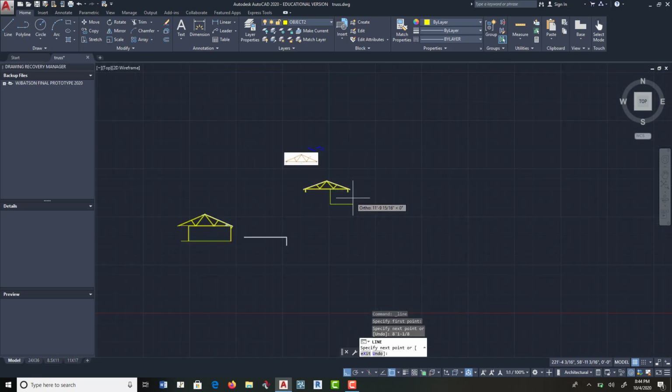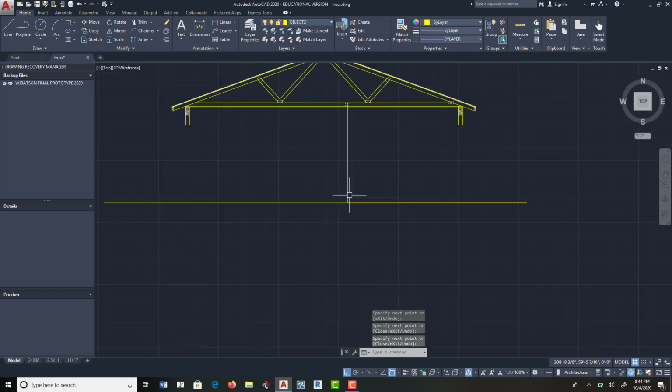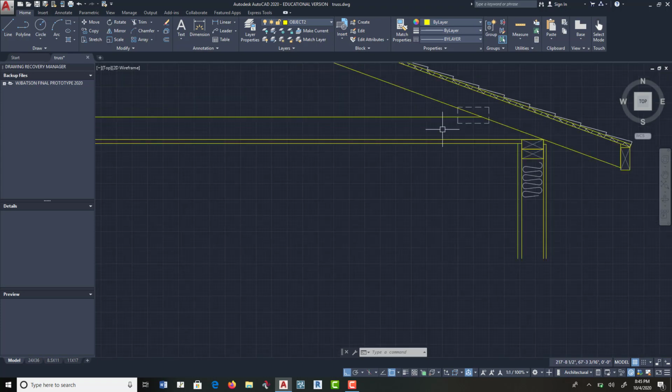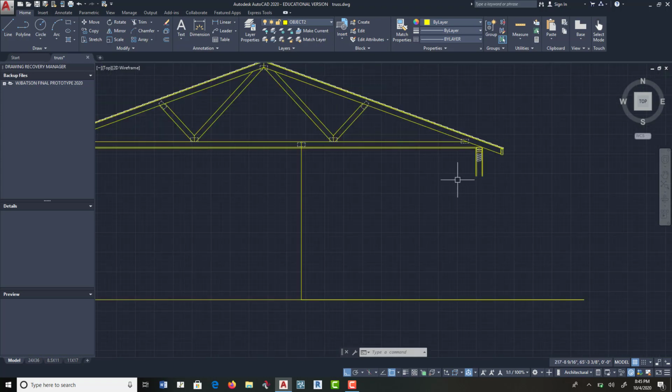And that's our bottom floor, because the drywall is 8 feet. You have to have a 1/2 inch gap at the bottom for expansion and contraction, so that's 8 feet, 0.5 inches. And then you have the 5/8 of an inch at the top. So 5/8 plus 1/2 inch plus 8 feet is 8 feet, 1 1/8. Okay? So now you can extend your walls down there.